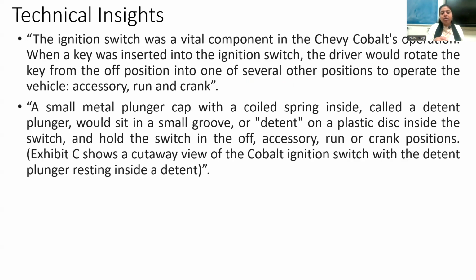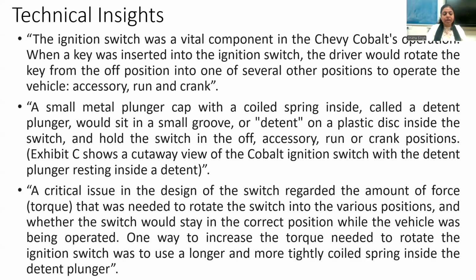And there is a small component called the detent in this ignition switch. The problem has been found in those particular components, the detent and the spring. These two components were found to have an issue. The critical issue in the design of the switch regarded the amount of force that was needed to rotate the switch into the various positions, and whether the switch would stay in the correct position while the vehicle was being operated.